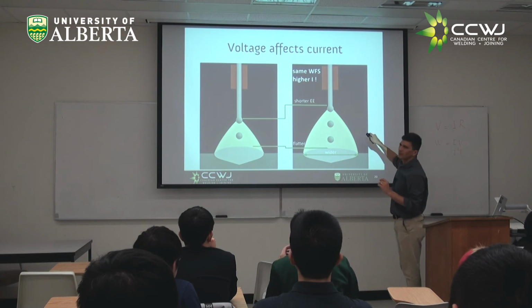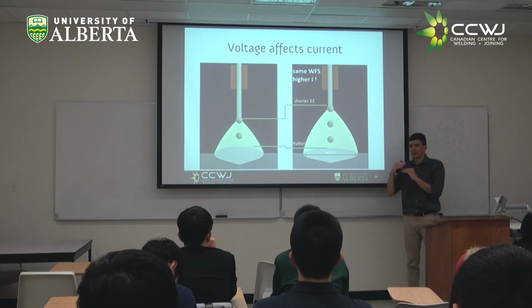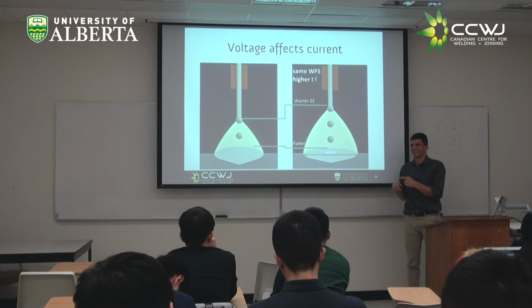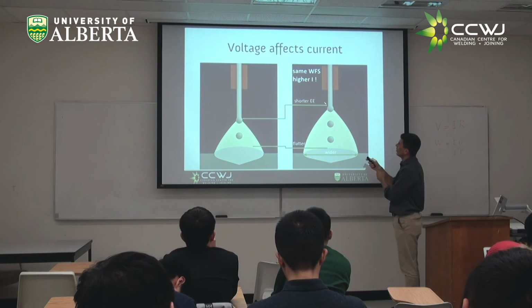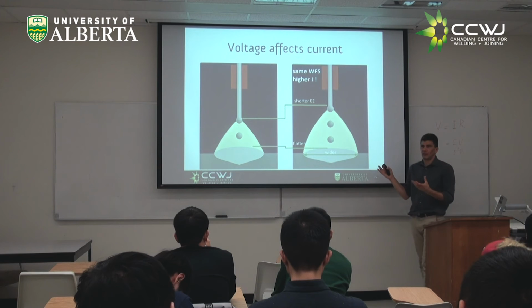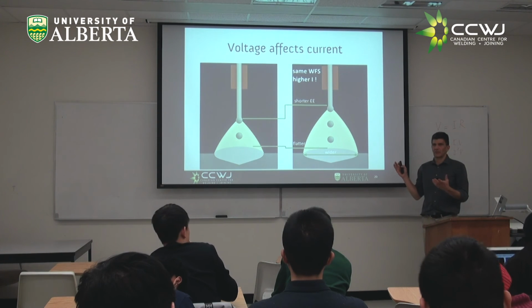Electrode stick out, shorter. So I'm generating less energy at the electrode stick out. So in theory, unless I increase the current, I cannot melt. And I increase the current, and when I increase the current, everything goes up, but especially I would have more energy deposited at the anode. You follow me?